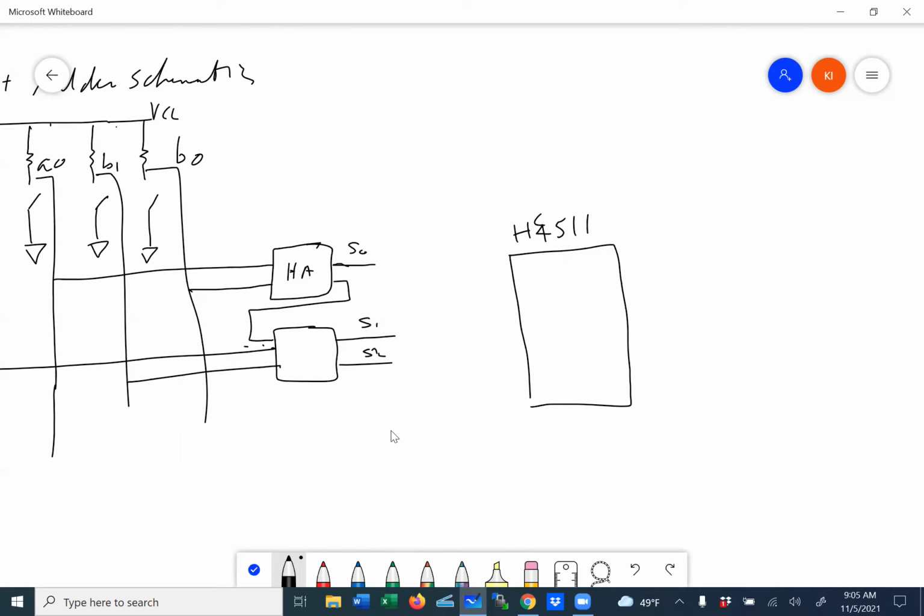And when you do that, you take this one and put it in the least significant bit, and this one in the next significant bit. So let's say data 0, data 1, and this goes to data 2. If you remember, that chip accepts 4 bits. So the 4th bit, you've got to ground it, because this only goes to 6. If you write 6 in 4 bits, the most significant bit is always 0.